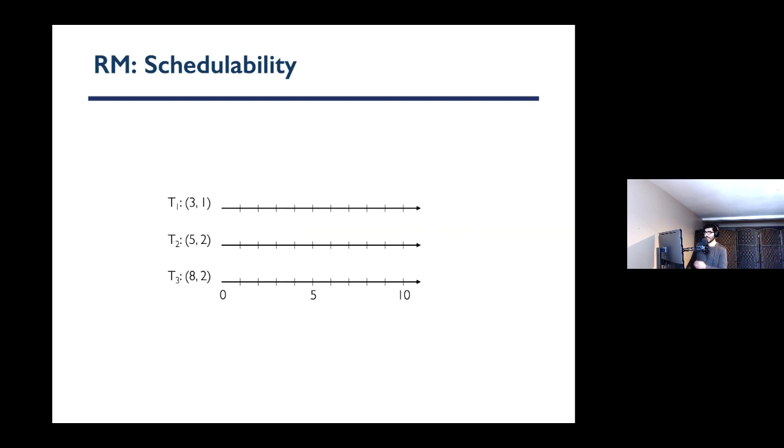Oh, you mean, and it would be lower than task 1, but even that, you could find situations that it actually works. So we actually will talk about it, but one example that comes to my mind is, let's say task 1 and task 2 have period of 10 but execution time of 1, and task 3 has period of 20 but execution of 2, and this would still be feasible.